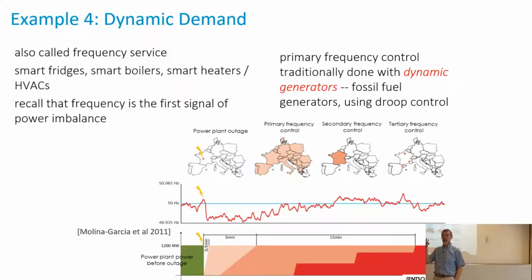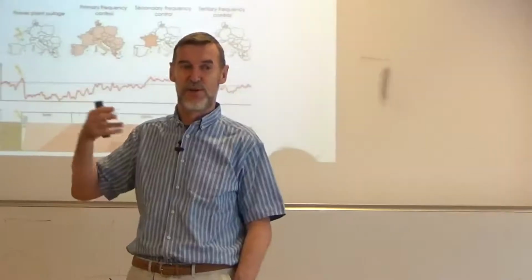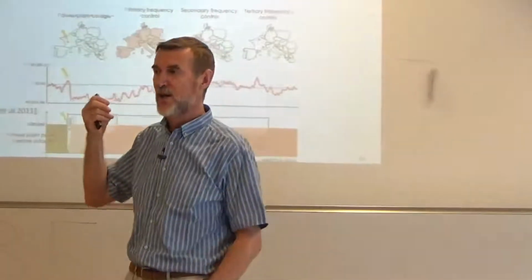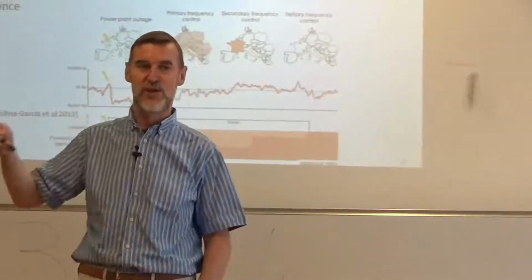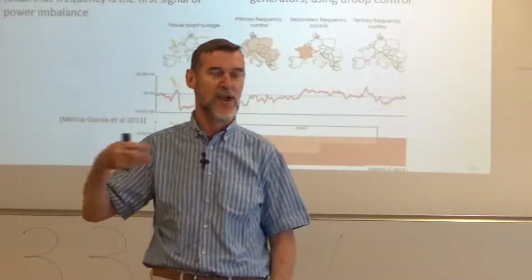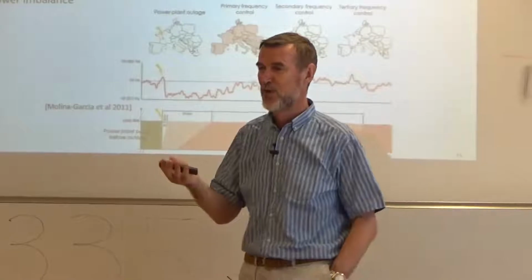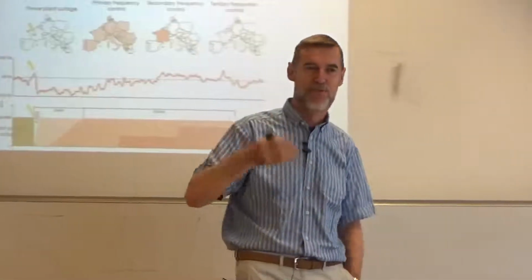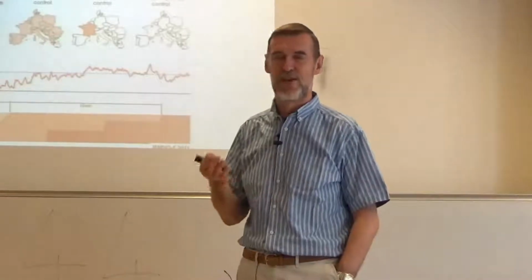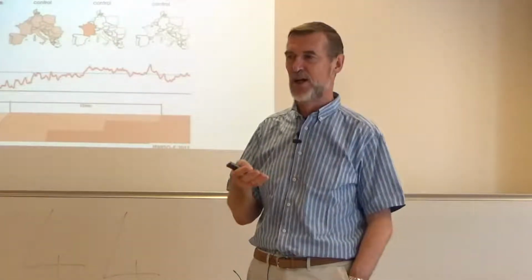So whenever we switch on boilers, for example, if there's a football match in the UK and during the break everybody switches a boiler on, the boiler is 2 kilowatt times 2 million, that makes 4 gigawatts, right? So football match break, plus 4 gigawatt. Then you don't have time to call the market to do things.